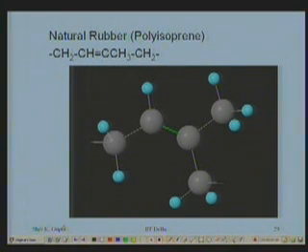It's a naturally found material, polyisoprene. How do we extract it from the tree, the rubber plant? It's taken out in the form of a liquid. So at room temperature, these chains are flowing, translating with respect to each other. So condition number 4 is already satisfied. Chains are translating at room temperature, so as it is taken out, it's a liquid. And in this form, I am not able to use it as an elastomer, right? Alright.